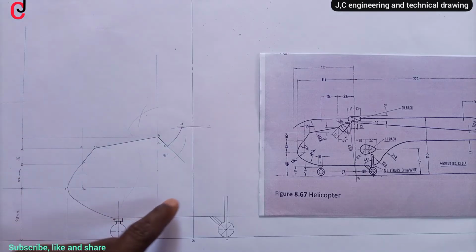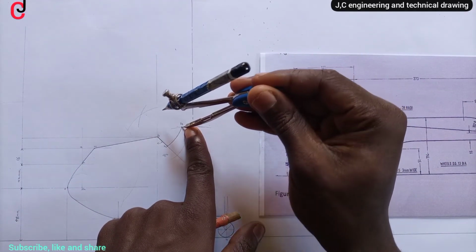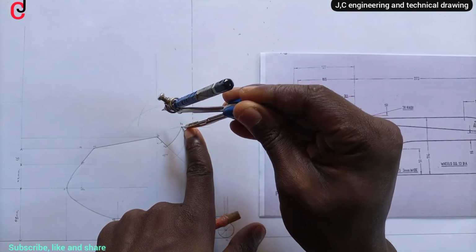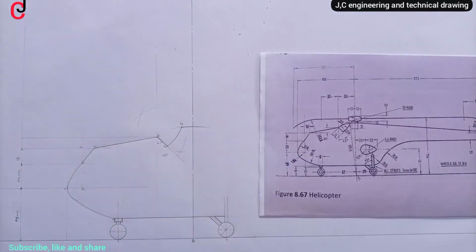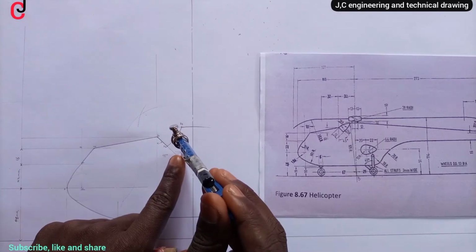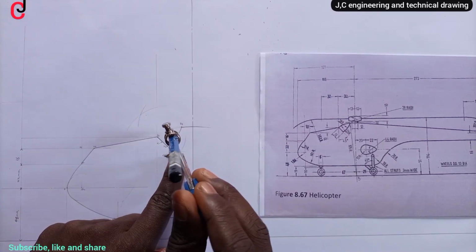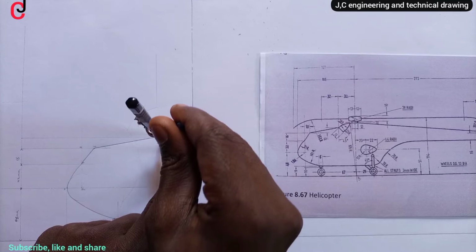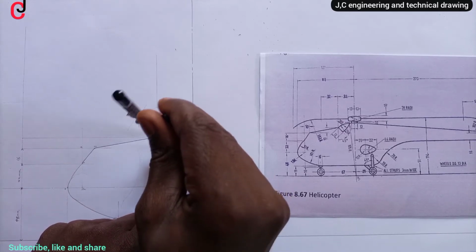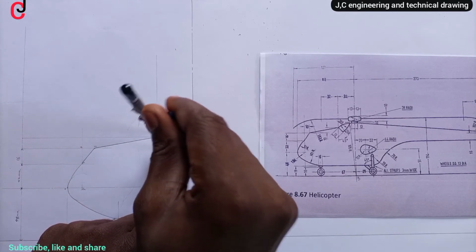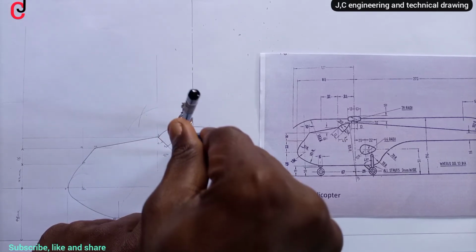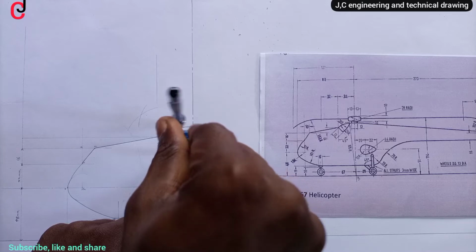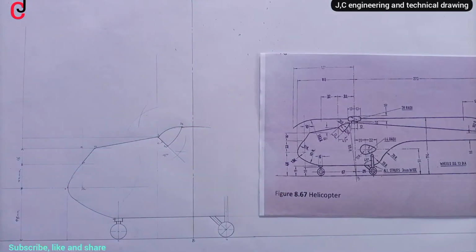Then we'll place a compass pin at point B3. We'll bisect the arc. Now using the point of the intersection, still on radius 25 millimeter, we'll draw the arc. You can see it touching that.